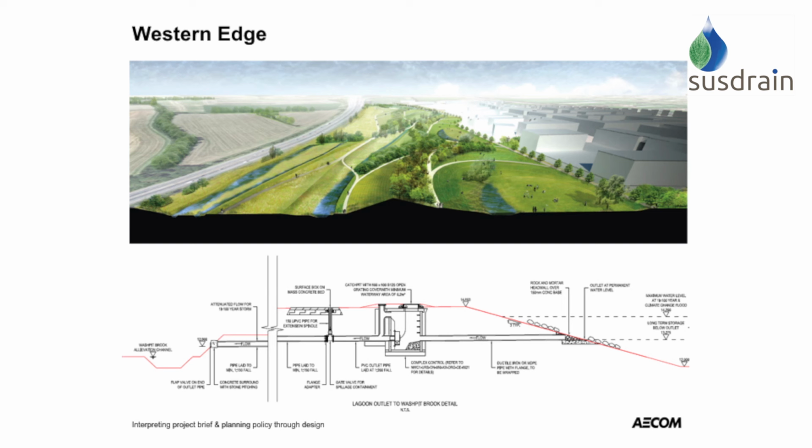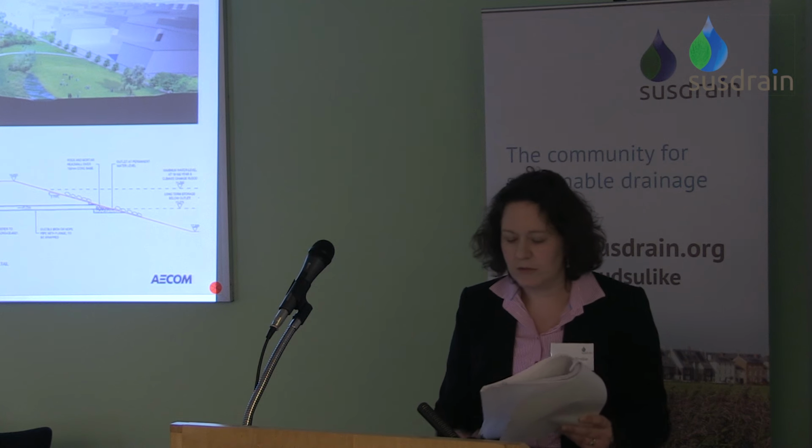We incorporated into the scheme a complex control to ensure that the discharge from the lagoon to the relief channel, over here, is maintained at greenfield runoff rates with the outfall set above the 1 in 100 flood level in the relief channel.